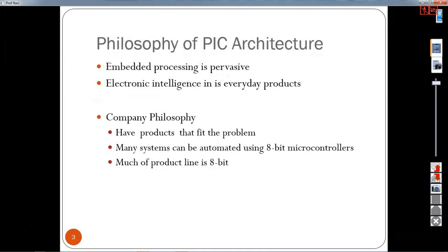And if you look at the applications, for engine control you can use a 32-bit microcontroller. For transmission control, you use a 16-bit microcontroller. The audio system uses 16-bit, and the anti-lock braking system uses 16-bit. But up to 50 applications in the automotive sector use 8-bit microcontrollers.